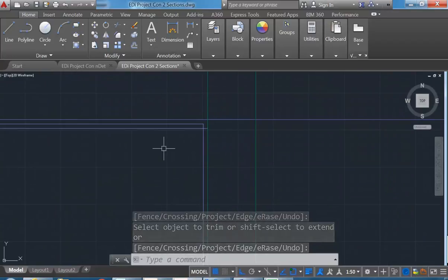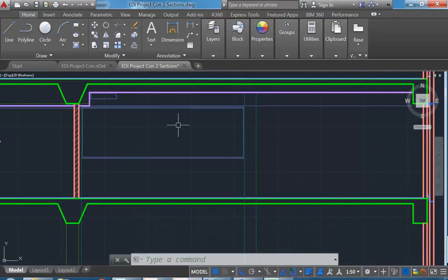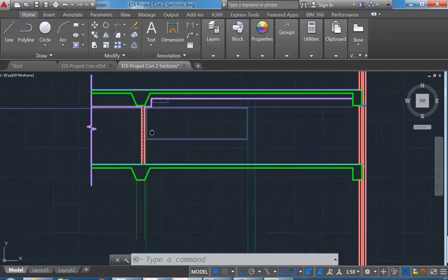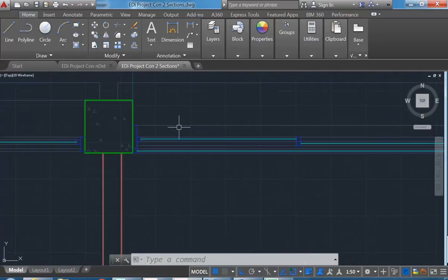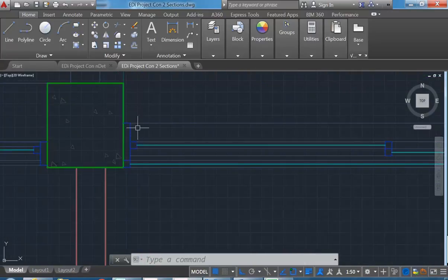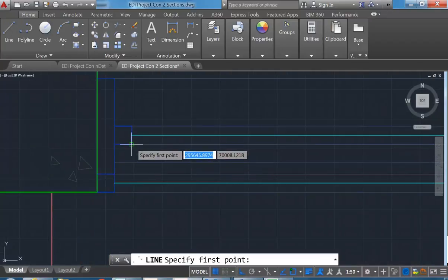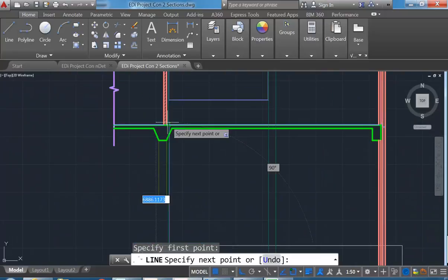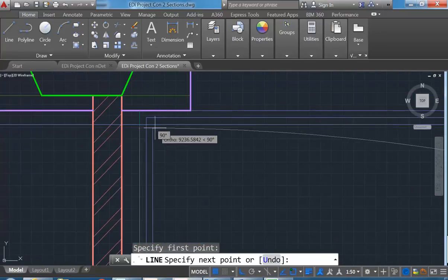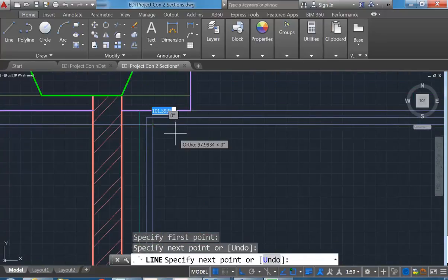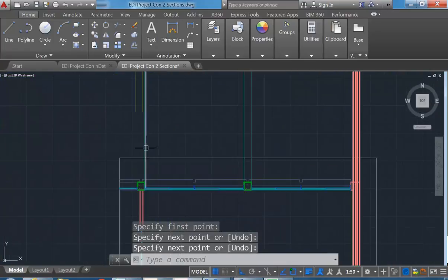Okay, so this line then is the only bit visible at the top of this frame, and then we've got these lines. So you're just projecting lines from the plan up to connect with things that will join to lines you've drawn from the section. So here, that will join to there, and again, just copy across.